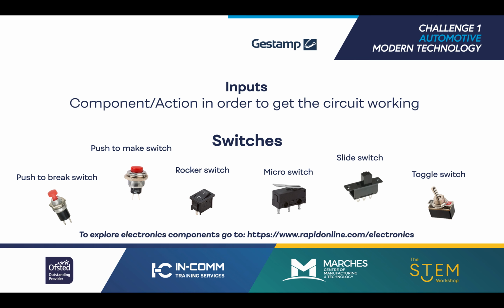A push to make switch works in the opposite direction. So the circuit will only be activated if you hit and hold that switch down, but you've got to hold your finger on a push to make switch. So there's only certain types of applications where you'd want that type of switch. For instance, if you've got a hand torch, you might want to hold the switch to shine the light. But if you want the light to be permanently on, you need to look at a different type of switch.